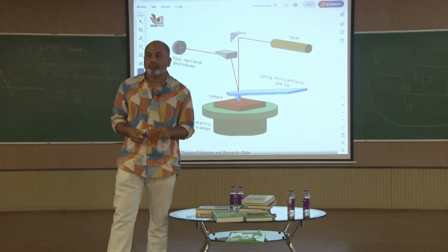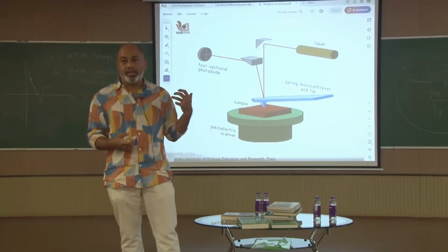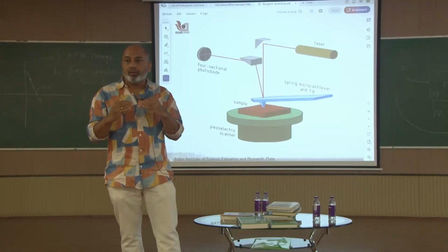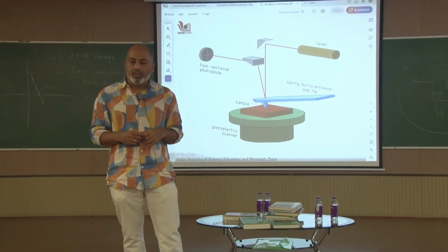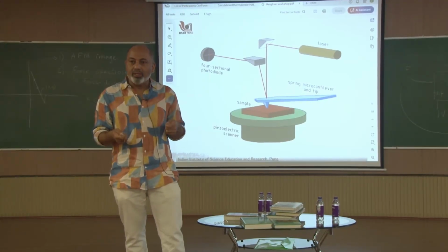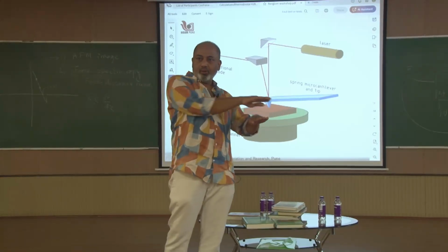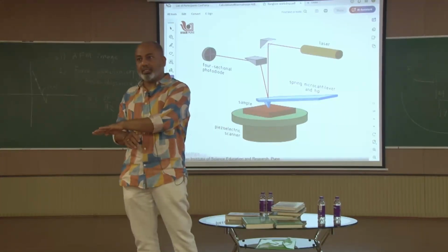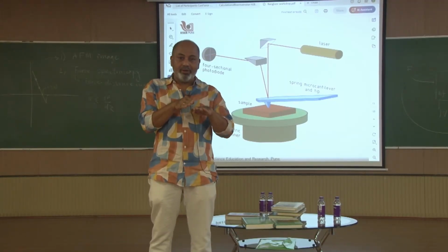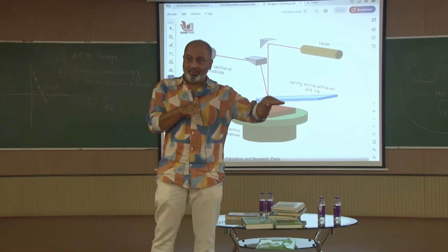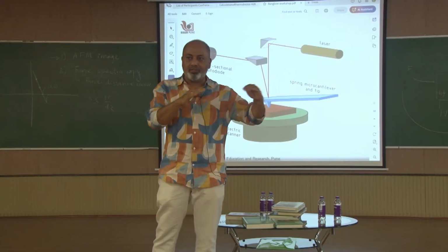But do you use some standards before doing this? Yes, of course, there are these standard samples, nanoscale gratings. You first image them, before testing the sample, and tune your PID controller so that, as I said, while going this way, the topography line should match while coming this way. Of course, while going this way, the topography will look a little different from while coming, so that difference will happen a little bit, but mostly they should match each other.